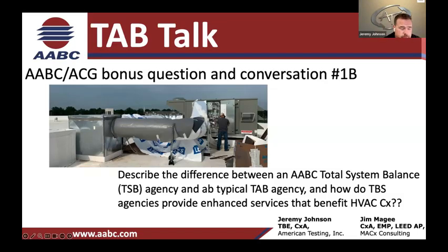Once again, other things that we've done, connecting the startup on equipment and commissioning of equipment, is sometimes getting some points, getting some details before a system's ready to be turned over to us, right? Is an air terminal unit, right? Pick up a couple points. Hey, what's the damper position? What's the air terminal reading, right? Those 2 points in itself can tell you a lot about how the system's performing.